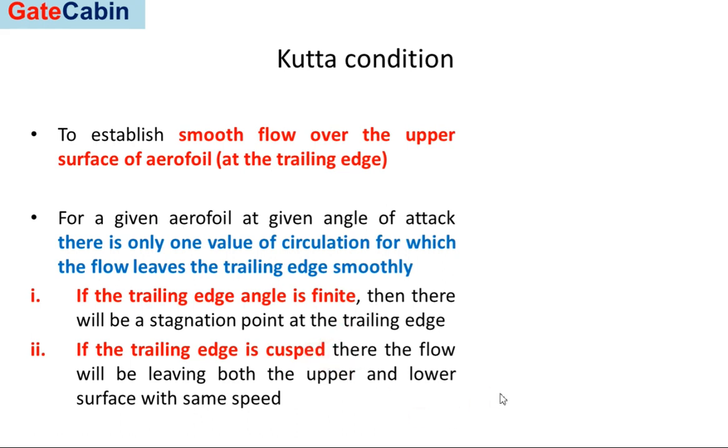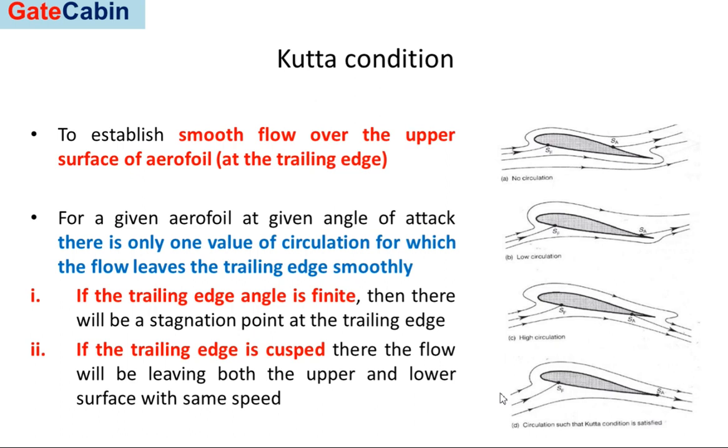And most importantly, we can visualize how an increase in the value of circulation helps to delay, or move backward, this second separation point. In the first picture, it is near almost one fourth of the distance from the trailing edge, and as the value of circulation is increased, it moves in the backward direction.